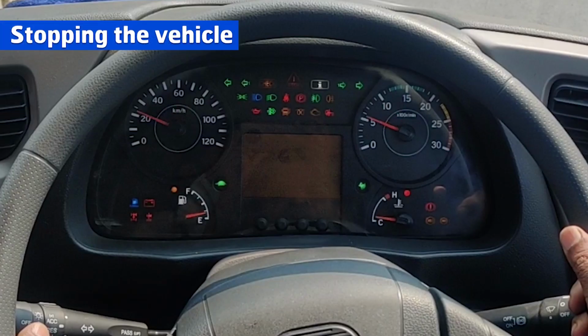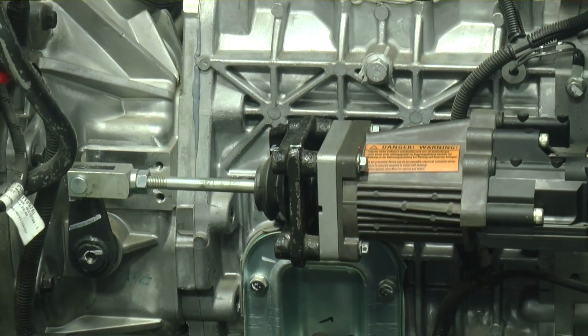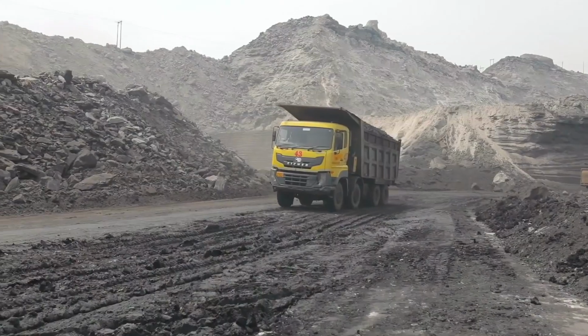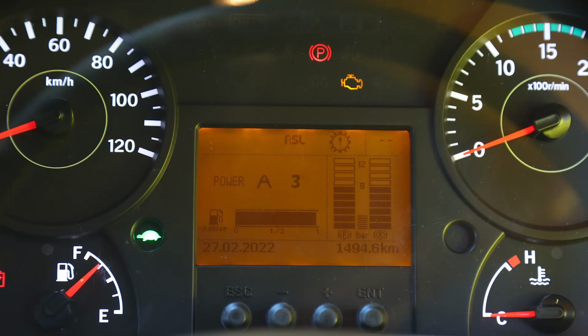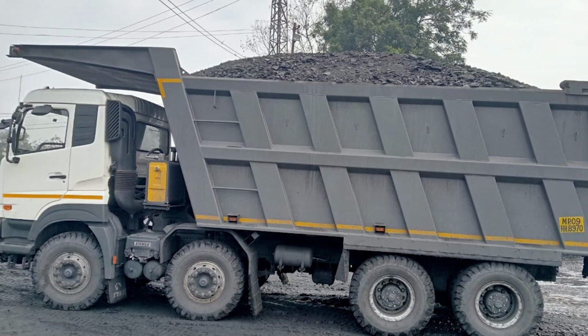Stopping the vehicle. When the vehicle speed decreases towards 0 and a gear is engaged, the clutch will open automatically by the SLU to prevent engine stall. When the vehicle is stopped while in automatic mode and a gear is engaged, the SLU initiates a shift to the appropriate starting gear automatically, depending upon the load.